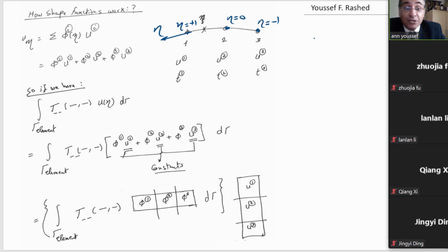Okay, and actually we change any curved element to straight element. This is called natural coordinate or intrinsic coordinates. Okay, this is eta equal +1, eta equal -1, and sometimes you call it xi or zeta or something like that. It is not a problem, the symbol we use. So at these points, displacements are defined here. U at 1, U at 2, these are the nodal values. This could be Ui, okay?